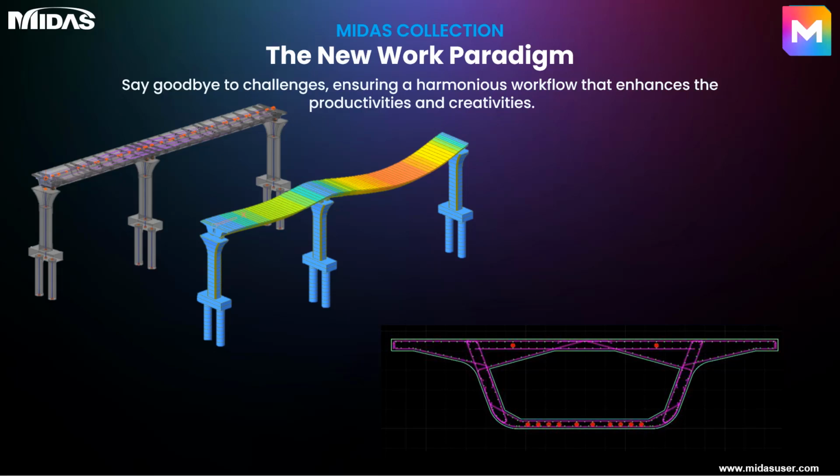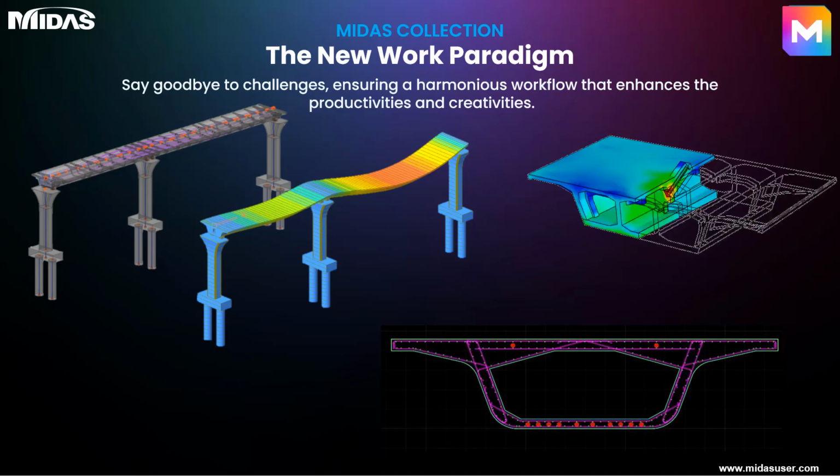The rebar data was transferred for modeling in CIM, and 2D drawing deliverables were generated by linking CIM to CAD Infra Design. For a more localized analysis, 3 segments were imported into MIDAS FEA NX as solid elements, including the reinforcements and pre-stressing cables, modeled as embedded truss and tendon elements respectively. A non-linear smeared crack model was used to study the crack propagation in the segments, while the rebars and tendons were modeled with linear material properties. After the detailed analysis, crack propagation was observed near the anchorage blocks due to the pre-stressing, emphasizing once again the need for detailed analysis. Thus, with the MIDAS bridge collection package, we can bridge the gap between different entities involved in the analysis and design of a bridge.